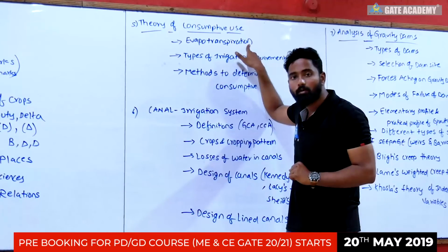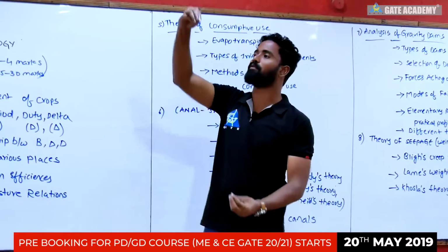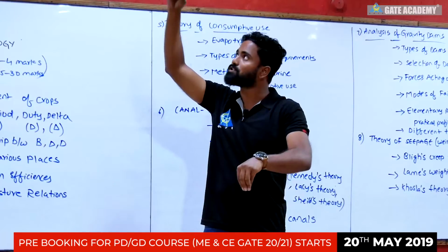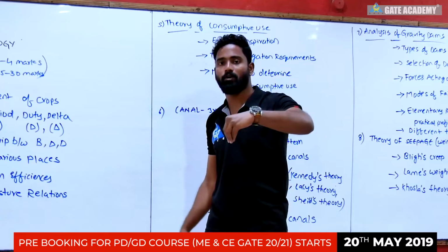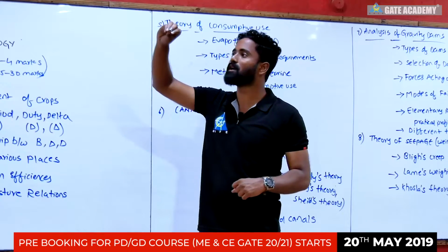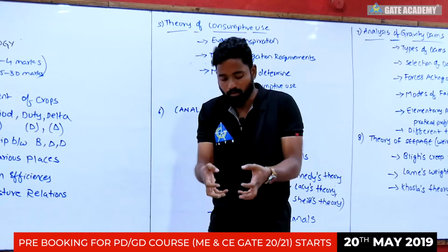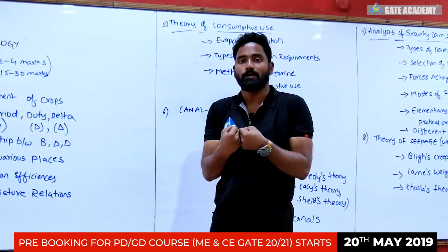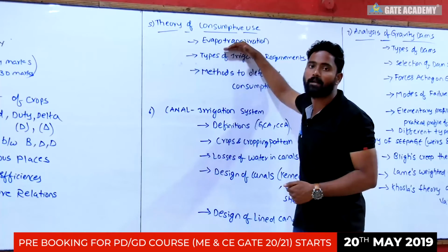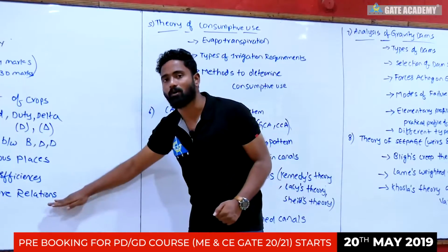evapotranspiration. Based on evapotranspiration, this amount of water is evapotranspirated when you provide this amount of water. So if you provide 10 mm of water and 2 mm is evapotranspirated, then if you measure 2 mm, you say that 10 mm of water is required, or 10 mm of water is absorbed by the plant. That is how it is calibrated. We calculate evapotranspiration, calibrate it to the amount of water required in the field, and then use that in the soil moisture relationship.